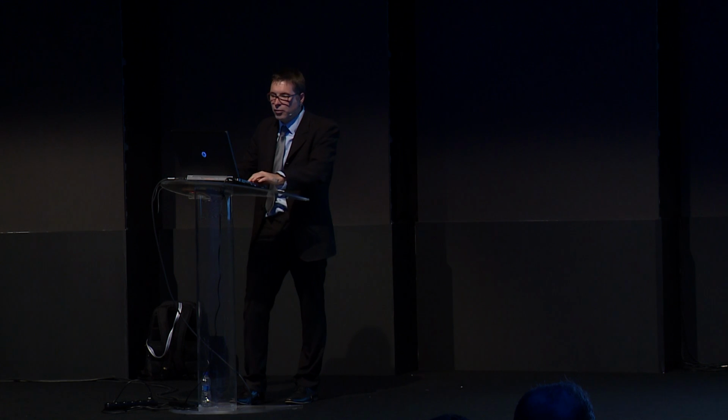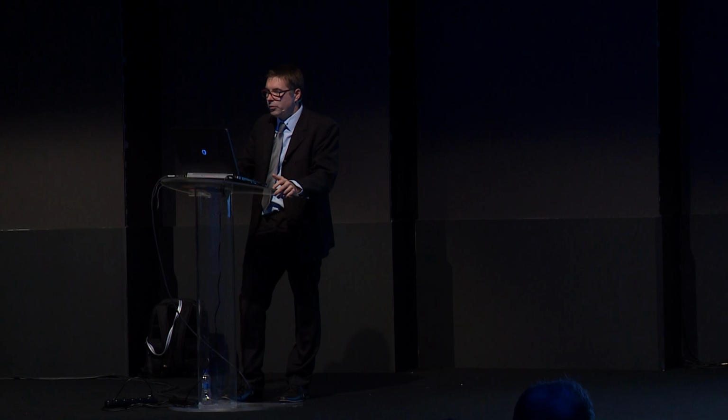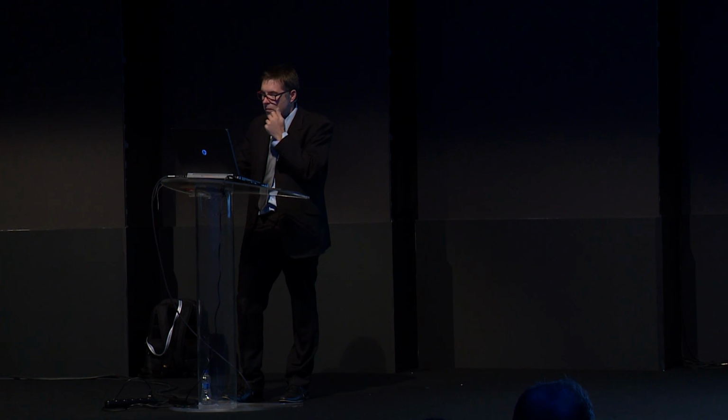There is nothing inside. I've got only the sun path, only that. Oh, yes, I've got something I created inside, an adaptive component, but it's a family composed by 4 nodes, okay? Now, if I use Dynamo, I will remove this. If I run Dynamo in Manage Tab, and I will run my script twist tour.